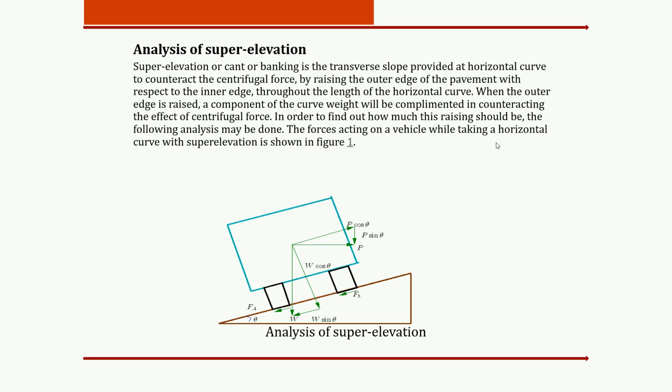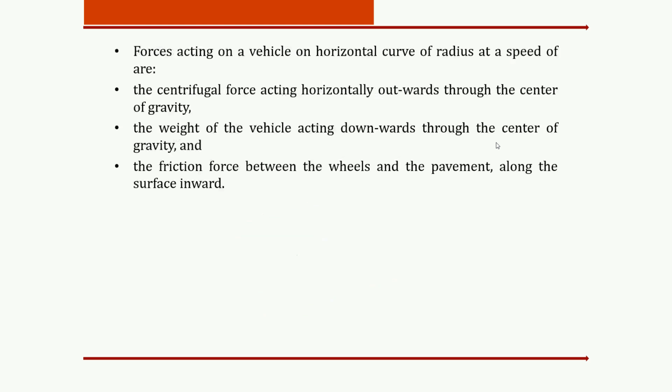And we know that as per the laws of mathematics, we can balance the super elevation on the road. If the counter force cannot be balanced, then there is a chance of skidding or slipping of various vehicles on the road. So this way super elevation and centrifugal force play a very important role in the design. When we are providing the design, a proper design of super elevation is required.